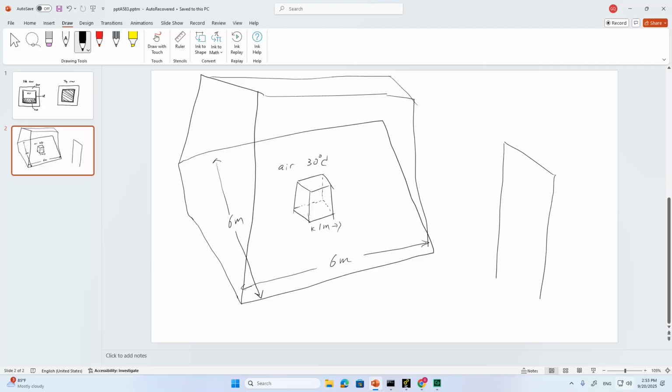Okay, so I will create another box, or more precisely, I will create some other surfaces to represent this room, this big room with our cooler at the very center of the room on the floor, so that here I don't really need to take care of the convection coefficient, because now I will also calculate the airflow inside the room, which directly gives us the heat transfer between the air and the cooler.